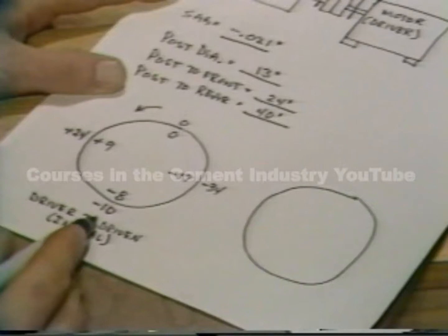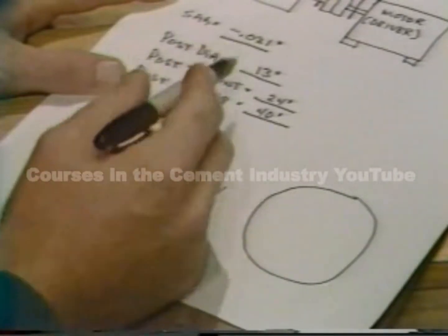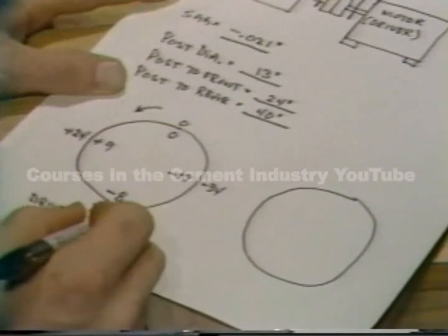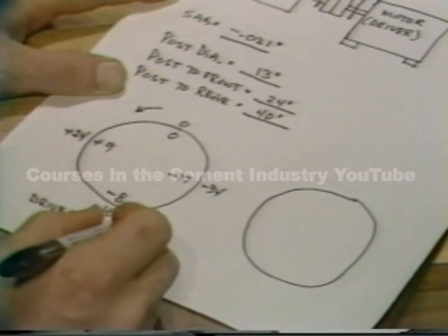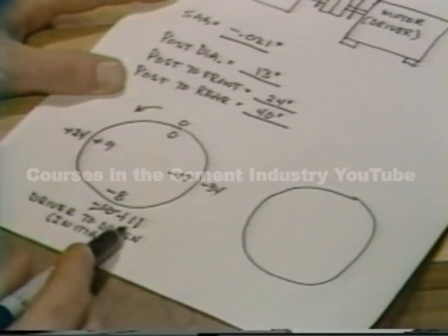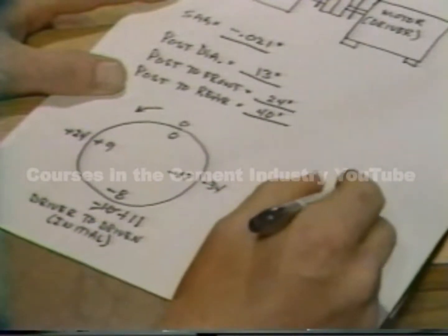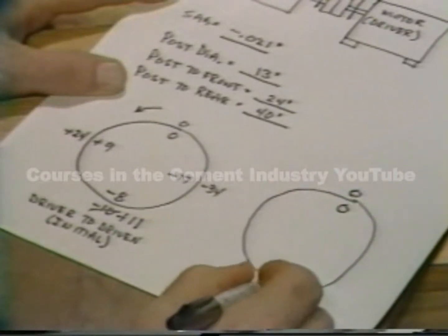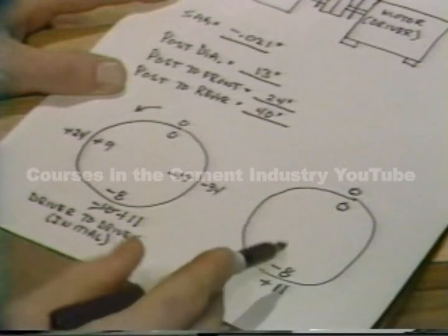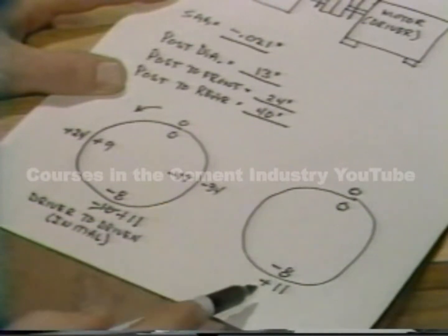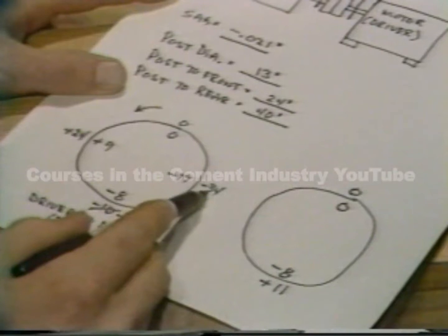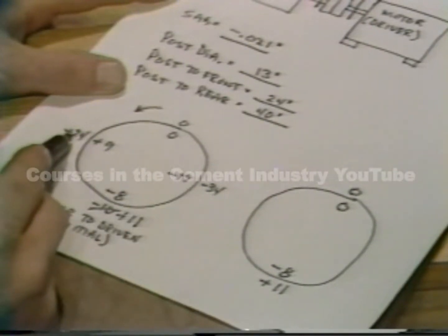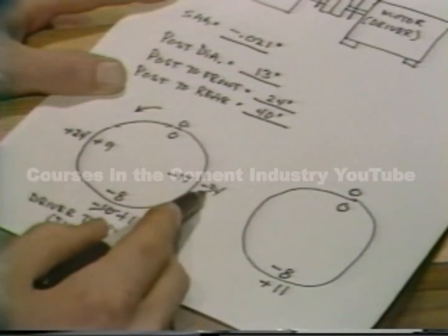To correct for bracket sag, the sag amount is subtracted from the bottom parallel reading. The remainder will be the actual deflection due to misalignment only. Then, to make the readings easier to interpret, it's a good idea to make as many readings relative to 0 as possible. We already have zeros for the top to bottom readings. Now we'll convert the side to side readings to be relative to 0. It's done by adding the side to side readings together, like 24 plus 34 equals 58.